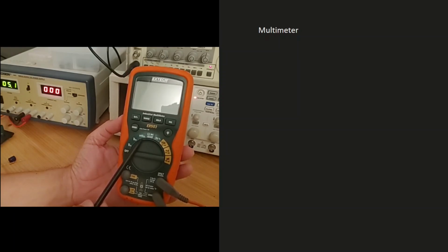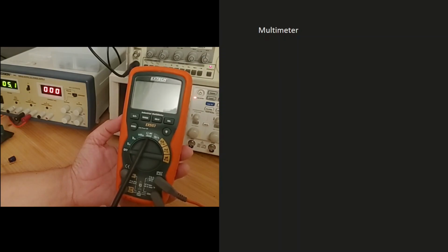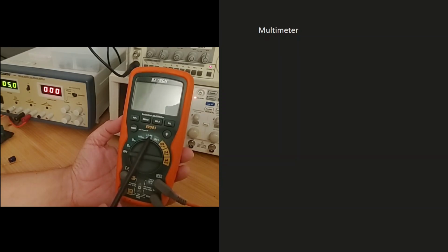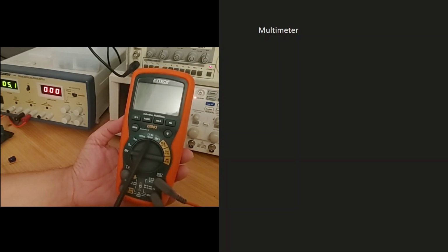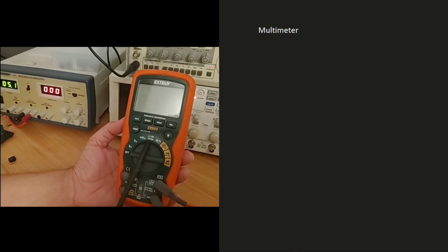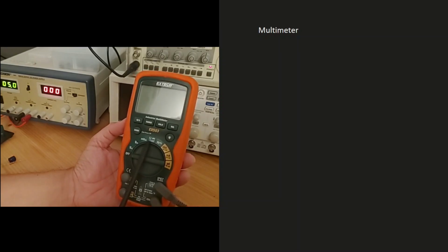This setting is for a voltage which is very weak or very small amount of voltage that we want to measure, so it's millivolts DC. And over here we have a few different functions. You will see the ohm sign, and this is for resistance, so we can measure resistance, and we can measure a capacitance, which is CAP for capacitance. We can also test a diode, which is this symbol of a diode, and it can also be used as a buzzer. And we use this buzzer to see the conductivity or verify connectivity of 2 points, and we will see that later how this can be done.